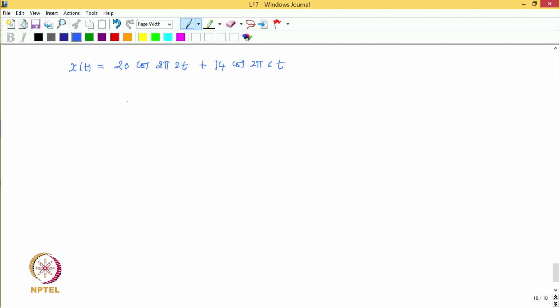Now, if we obtain the DFT of this, the signal was sampled at 20 hertz and a 1 second record was measured. Here we are representing the magnitude of the two sided DFT as a function of frequency f in hertz. The spectrum is defined over minus 10 to plus 10 hertz.